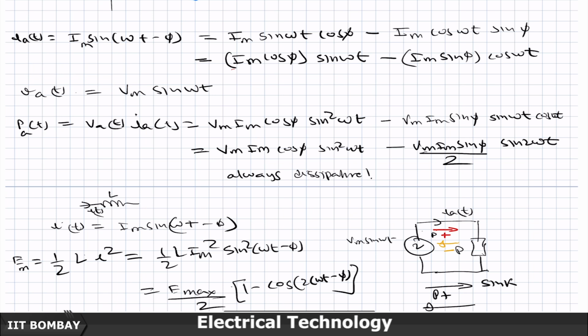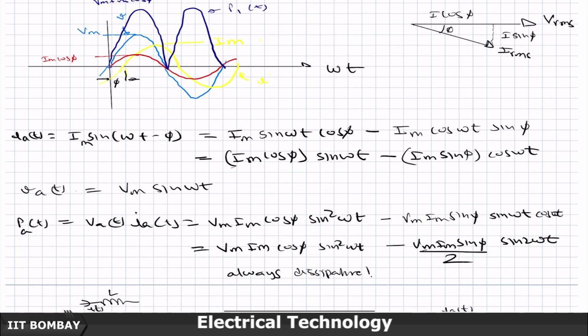Not to say completely out of phase, because if you reverse a phase you can probably say that is out of phase. So, this component is at quadrature, and therefore it creates a sin 2 omega t term, which has an average value over a cycle equal to 0, and hence does not do any good work.